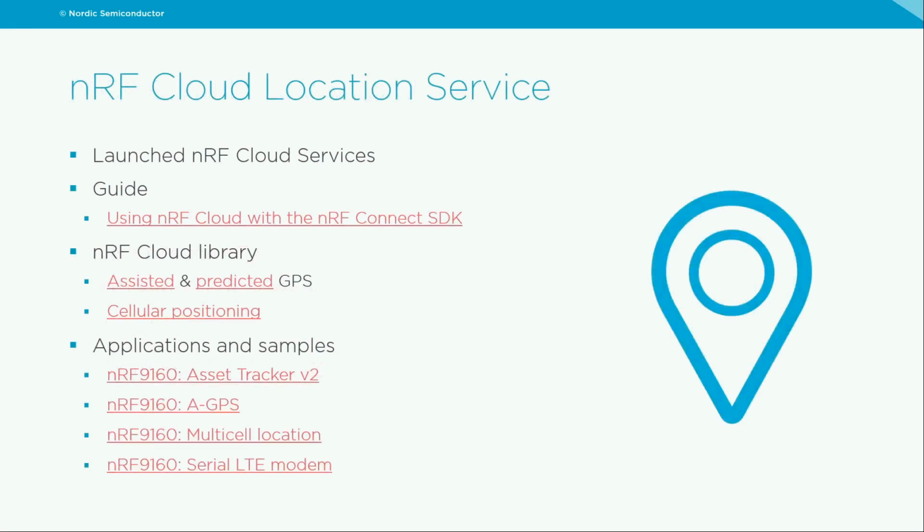Then we have the nRF Cloud services. So we recently launched nRF Cloud location services. So in this release of nRF Connect SDK, we also added a guide on how to use nRF Cloud with nRF Connect SDK. There is this updated nRF Cloud library that now contains all the functionality that's also part of the location service, like assisted GPS, predicted GPS, and cellular positioning using both single-cell and multi-cell technologies.